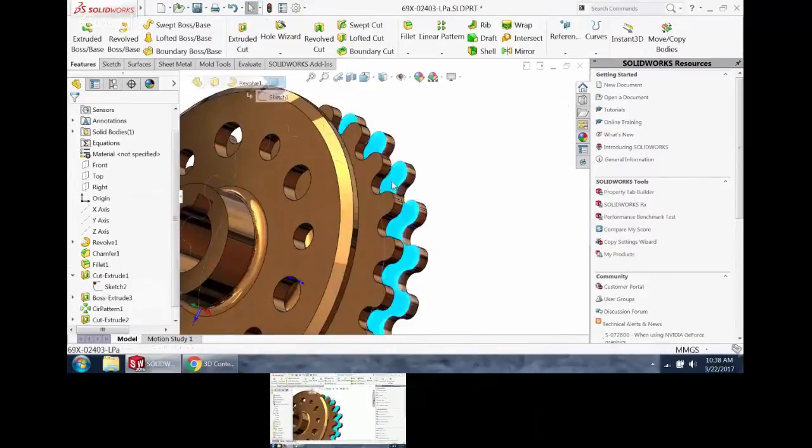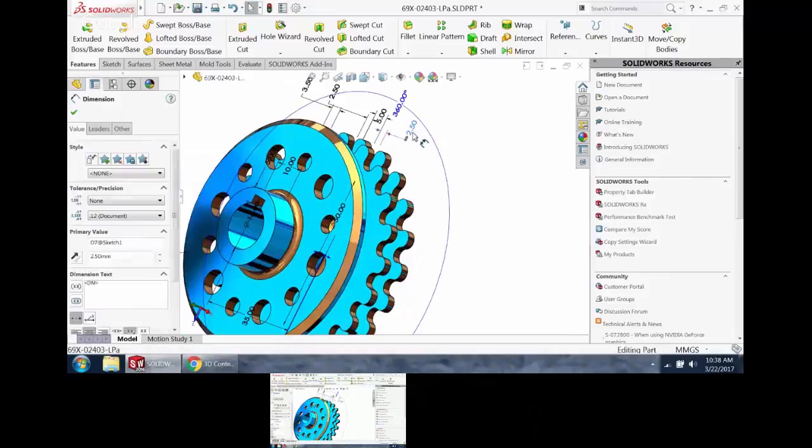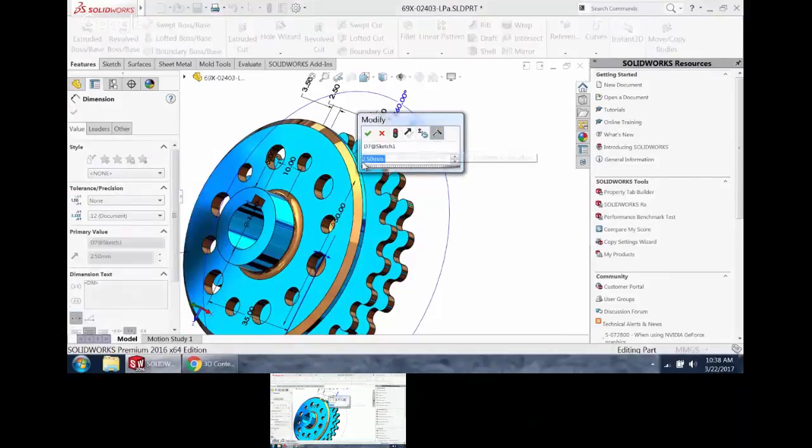Okay, another thing you can do with equations is you can also create a global variable on the fly. So if you type in equal, you double click a number, you start putting in stuff, you can have it relate to dimensions around it, as I was showing you. You can also say this equals and give it a name.